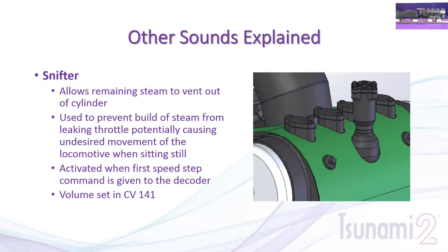Now, when I start to move the locomotive, you're actually going to hear a first chuff, and that first chuff is actually the snifter valve. And then when I stop, you're actually going to hear a slight ping. It's kind of like a marble dropping in a jar sound, and it's all pressurized based. There's no manual control of this. So listen closely here.